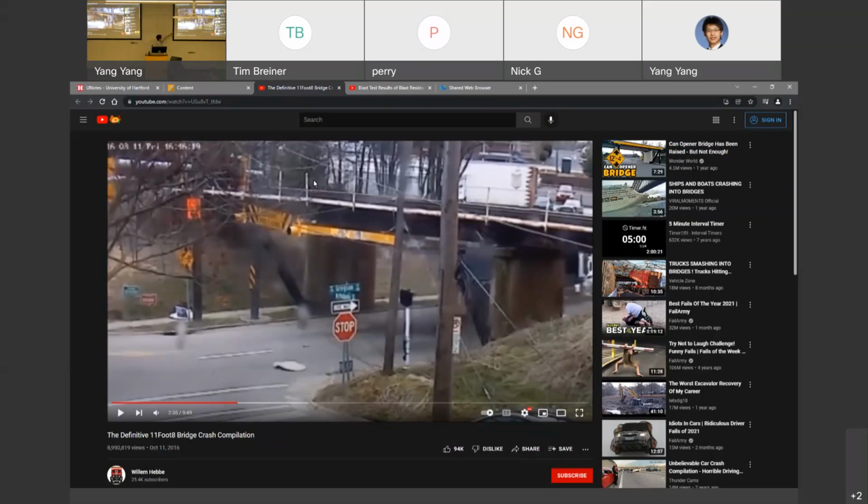And imagine if that bridge is across a river, especially a river with some ship traffic there. You want to consider the ship collision on the piers of the bridge. All of this impact of the dynamic load is a function of the load itself, as well as a function of the dynamic properties of the bridge itself.